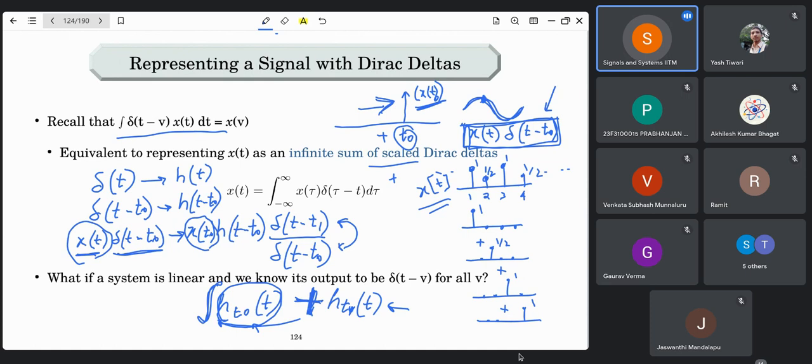So basically, this is all we are doing. We exploit the property of time invariance and the property of linearity to simplify this input-output relationship. You take an impulse, time shifted. Because of time invariance, the output also gets only time shifted, nothing else. And you scale it with some scalar, and that scalar turns out to be just one sample of your input signal. So the output also gets scaled by that scalar. Now you can change this scalar over time, by adding multiple time instances.